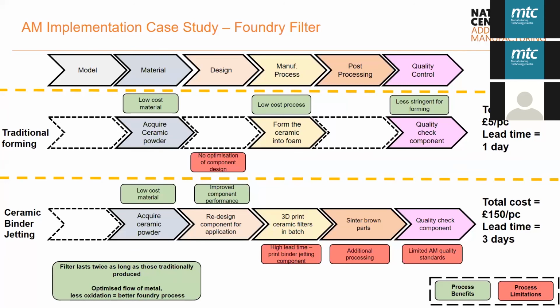If there is a great cross-sectional melting, then potentially you might have enough heat built up that you will see residual stresses and therefore need heat treatment. So most likely if it was LPBF, it will be heat treated. EBM is a technology that has been used for orthopedics as well.